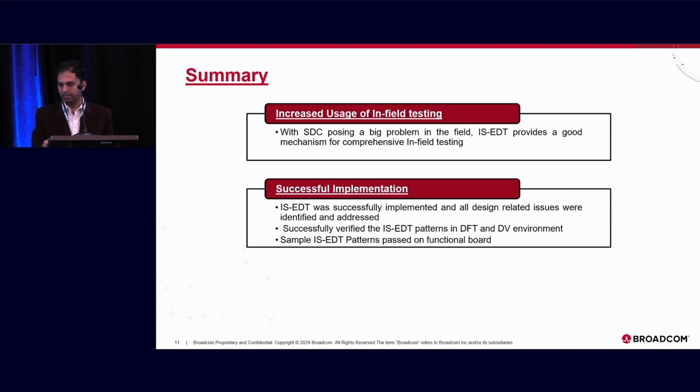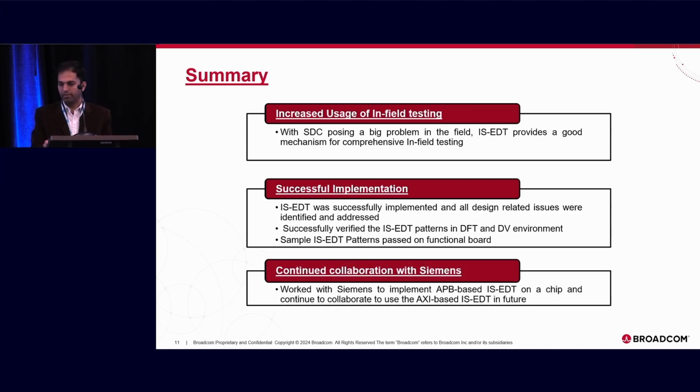We have done a successful implementation, and we have verified it properly in the DV environment and in the DFT environment. The latest result we have from silicon is that we have one sample pattern passing on the silicon as well, and we are working towards other patterns. When I say on silicon, it's on the EVB or the functional board. And we are continuing our collaboration with Siemens for the next gen, and even to enhance this thing.